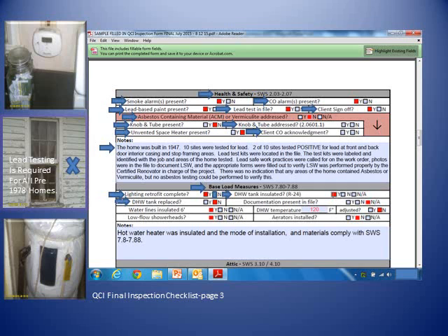Was the hot water heater replaced? In this case, it was not. If it had been replaced, is there supporting documentation in the file to justify the replacement? In this case, it does not apply. Now, were the water lines insulated going 6 feet out from the tank on both water lines? Yes, indeed, they were. You will also need to take the hot water temperature and record the reading, and note whether or not an adjustment in water temperature was necessary.